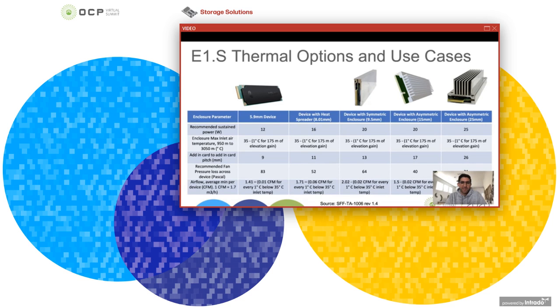So this is a really exciting form factor for a lot of reasons, because now you can do things like equivalent U.2-like performance in a much smaller form factor. In this form factor, with a 13 millimeter pitch and a 9.5 millimeter thickness, you can fit 32 to 36 devices across the front of a 1U. So you can have extremely dense I/O platforms with this form factor.